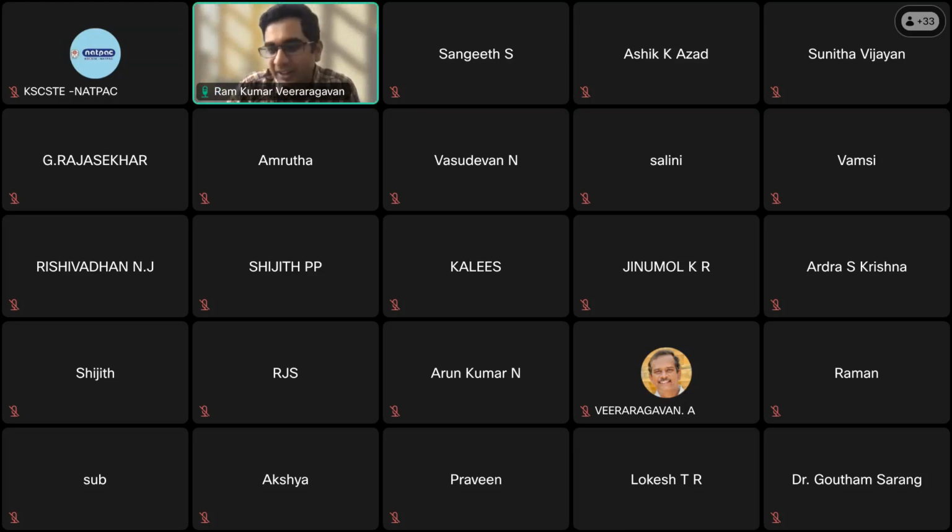Not that I'm aware of, sir. The standard, AASHTO T 324, the Hamburg wheel tracking standard, specifies to start off with 20,000 and go from there. So I'm not aware of a minimum number. Some states I have seen go as low as 10,000 passes. That's the minimum that I have seen from our past site visit experience. So it can range anywhere from 10,000 to 20,000 passes.